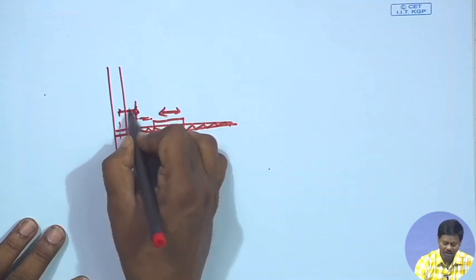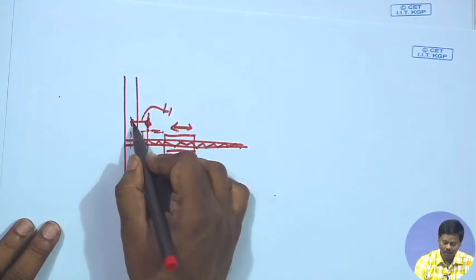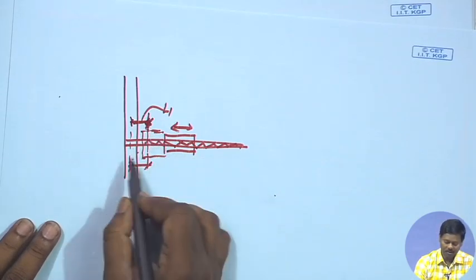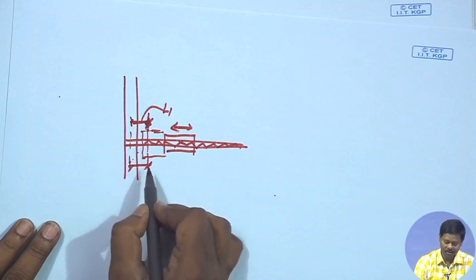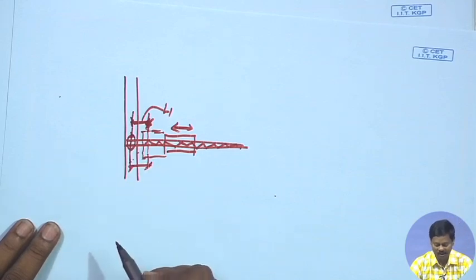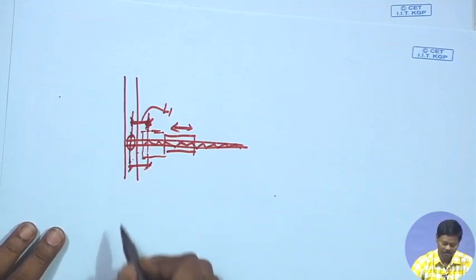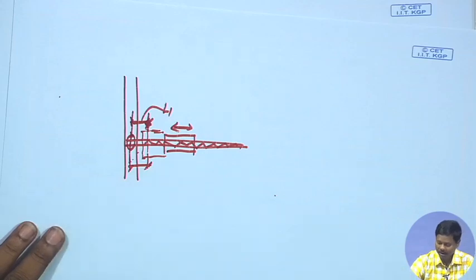then the load we can find out on the crane at a certain position, say L1. Because of the position of the load at L1 from one end of the gantry, we can find out the load on the gantry, meaning the reaction on the gantry girder. So, this will be the maximum load coming onto the gantry.